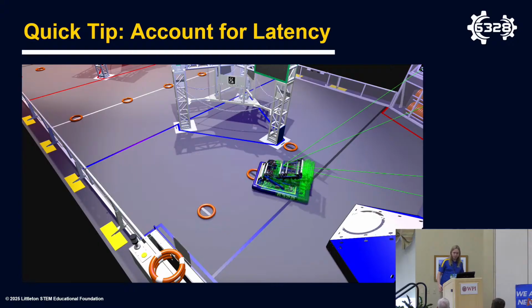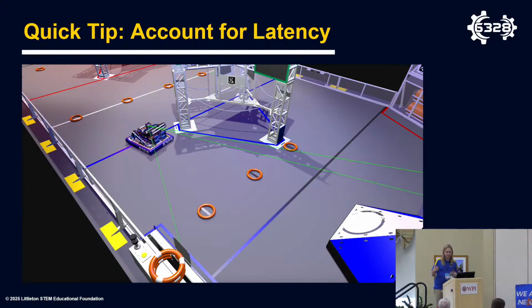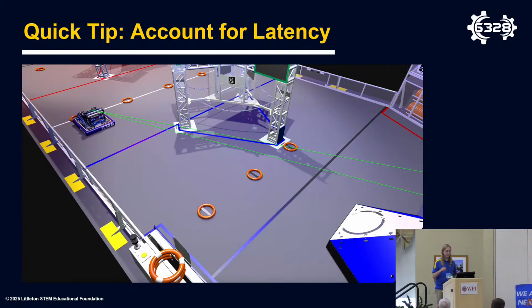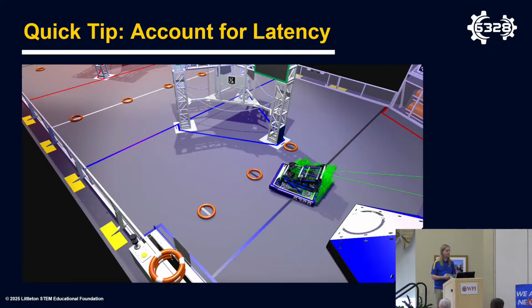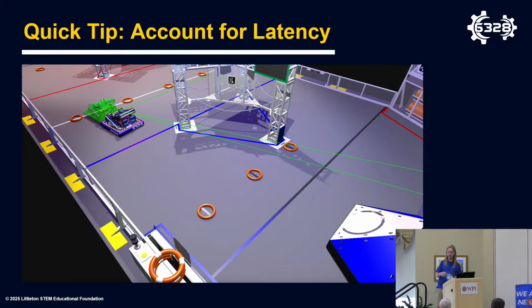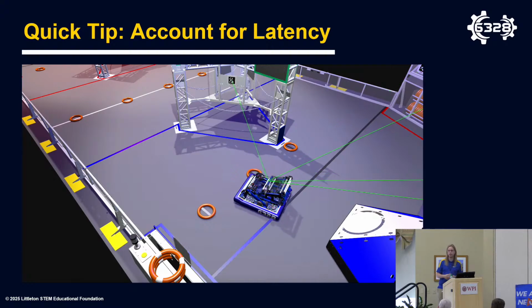Okay, then another important one. When we're talking about vision systems, between capturing an image itself and that detection result arriving at the RoboRIO, there's going to be significant latency. Depending on your frame rate, that could be up to a few hundred milliseconds. Here's a clip where you can see the robot moving quickly. Those pose estimates arriving at the Rio are shown in green, and when we're moving, they're lagging quite a bit behind the robot's real position. If you try to just integrate those poses naively, as you start moving, they will actually drag your pose estimate around and increase the error quite severely. And so you should check the documentation again for your chosen vision solution on how to properly account for that latency.